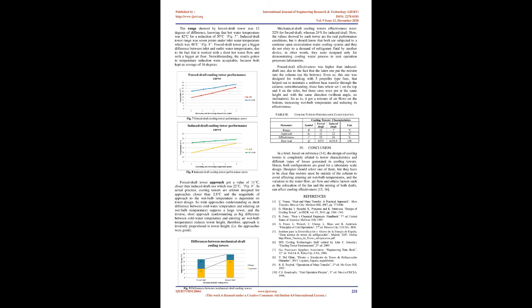This is why it may be necessary to know where the laboratory environment conditions were when the cooling towers were designed. Now, the forced draft Fig 5 and induced draft Fig 6 towers are shown, with their fundamental characteristics in Table I. In this case, the towers used a filling made of high-density polyethylene. Forced draft tower used a trickle pack filling of 5 mm, and induced draft tower used a horizontal filling of 1 mm, set with spaces between the top and the bottom of the columns, all of these defined by their height of unit transfer.